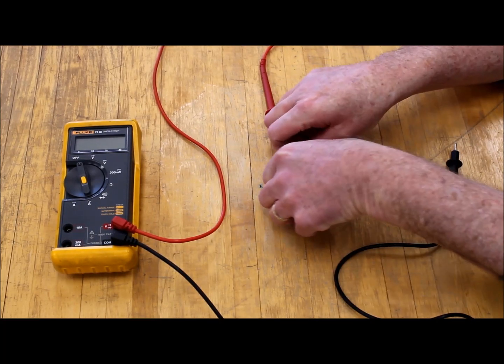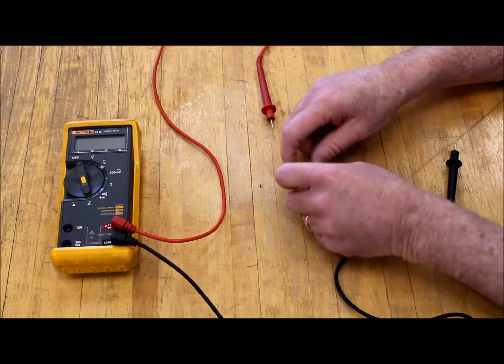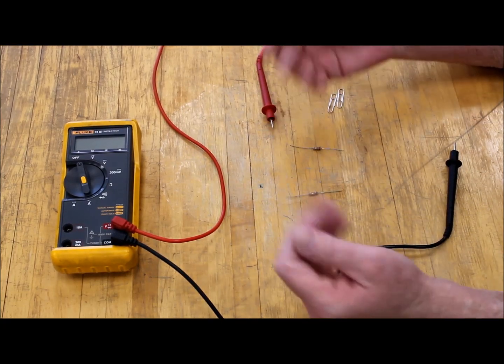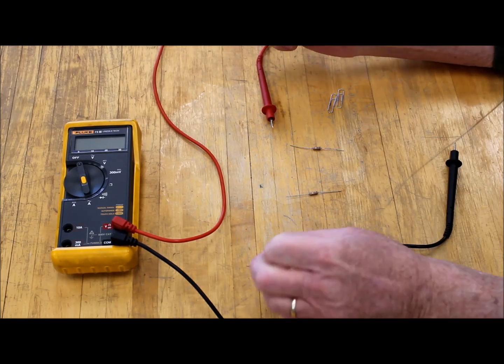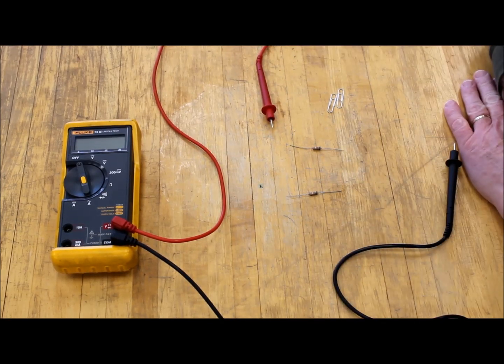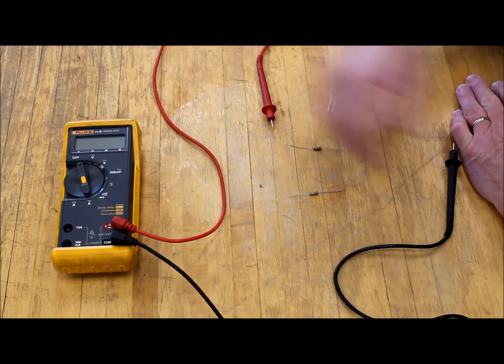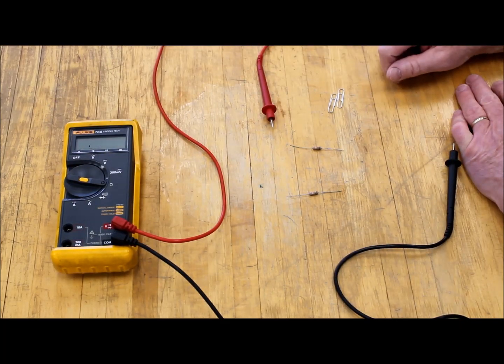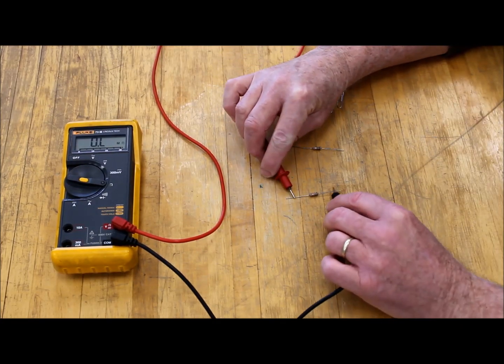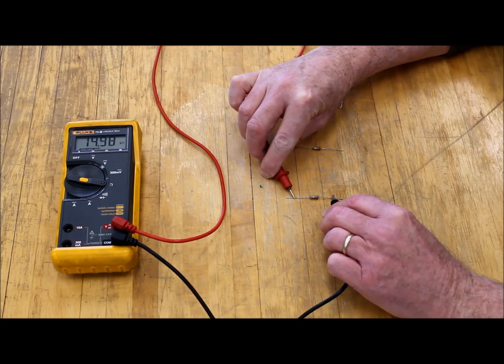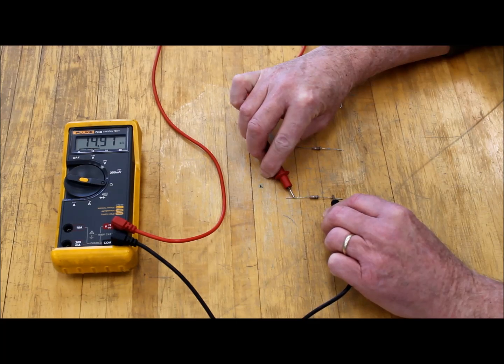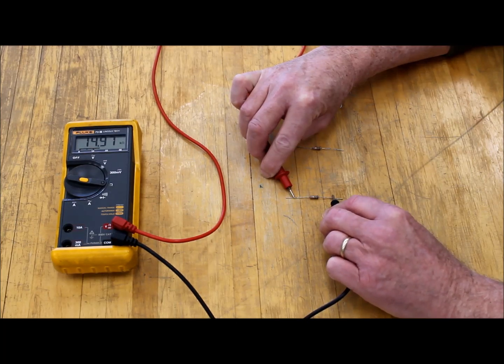I have here two identical resistors. First we're going to measure the resistance of each individually. Then I'm going to hook them together in parallel and see what the combined resistance of the two in parallel is. And we'll look at series too. So let's start by switching our meter on to ohms, and we'll look at the resistance of one of these. We can see that it's about 15 kiloohms, so 14.97 k ohms.